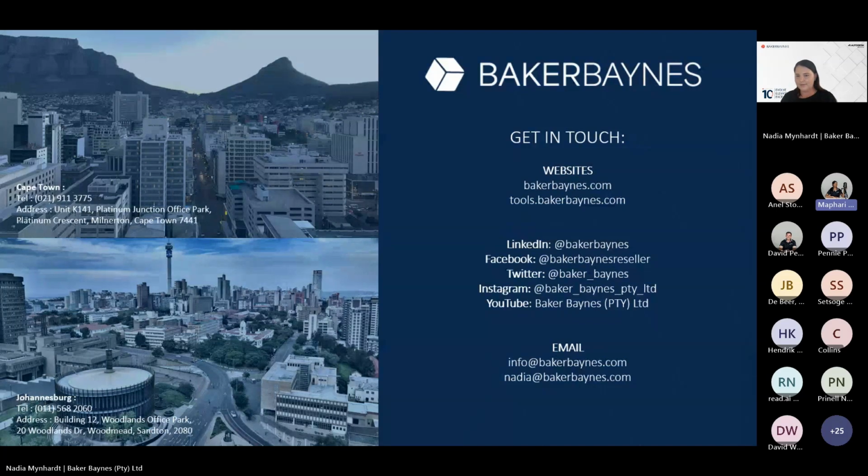Pranal asks: when creating families, for example the columns, can you create them in Revit and take them through to Infraworks? So, hi, Pranal. There is a workaround, which I will get in contact with you about, but I find it's easier to create the family, or rather part, in Inventor. If you try to import a part into Infraworks, a family for instance, it's going to pick it up as a model, so it won't be a parametric family. In that case, I would rather use Inventor or the actual infrastructure parts editor.